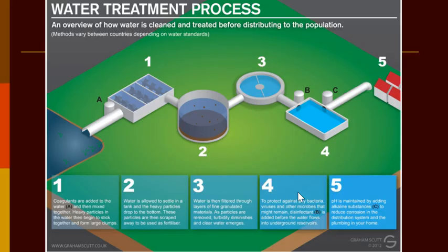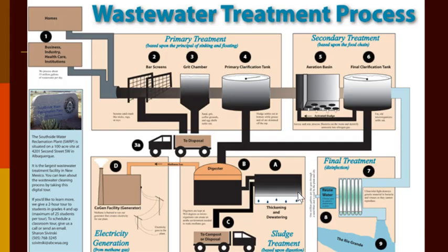Okay. All right, so in the water treatment process for wastewater, same thing. It's got to be cleaned. It's going to be cleaned in the same types of steps. You've got the filtration and the coagulants, and then in wastewater treatment, you're also going to have a biological component that you typically don't have in drinking water, and that's another change there. Then you're going to have to readjust the pH, and you're going to have to kill anything that's in it, including the bacteria that you put in it to clean it.